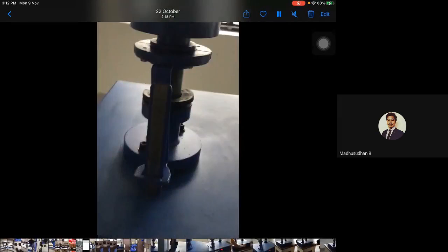It has increased to 20 mm height of the sleeve. Note down the speed parallelly. Similarly, you can use the scale to take the readings. If it has reached 30, note down the speed; 40, note down the speed; and 50, note down the speed.